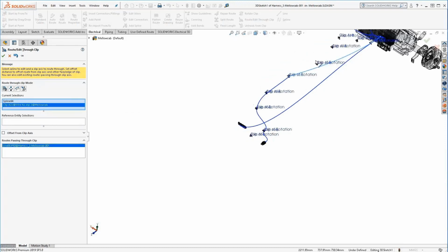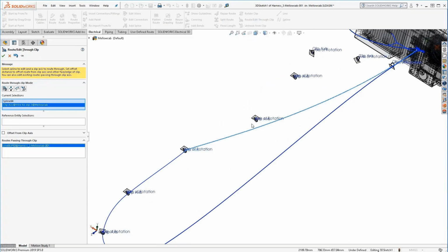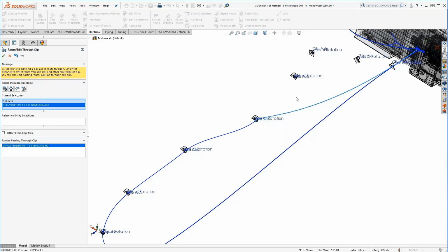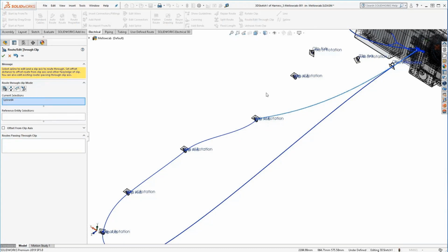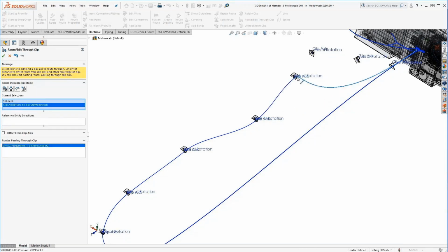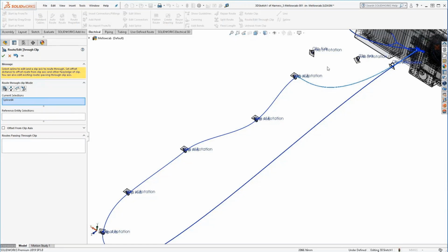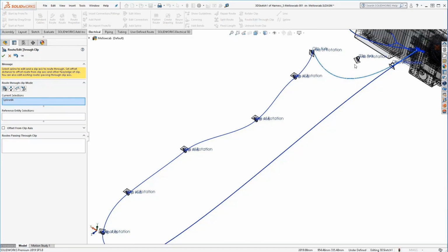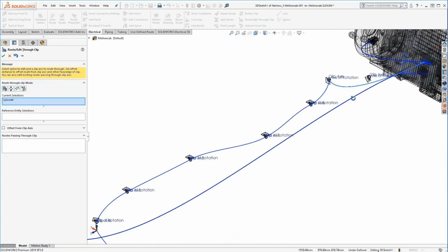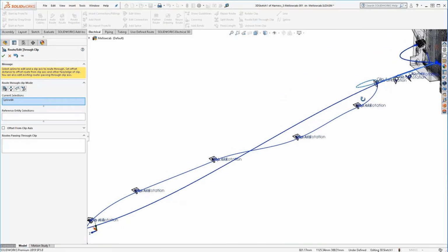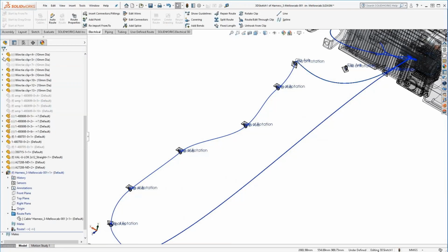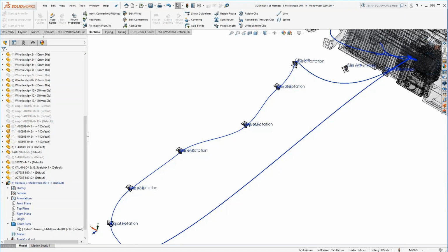Okay, so as you can see, you only need to edit the route, select the segment that you want to make pass through a specific clip, and then select the clip, and SOLIDWORKS is going to make it real. Okay, in some cases, like here, probably I need to move that around because it's not giving me all the information, or it's probably not the best view for me. The good thing about this route through clip is that you may cancel this anytime, and you may continue later routing this through the clips. So you see, just cancel that,